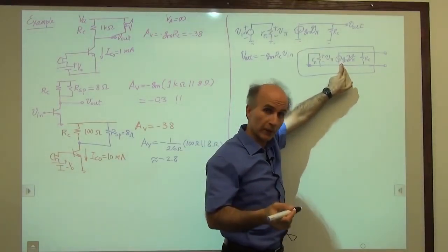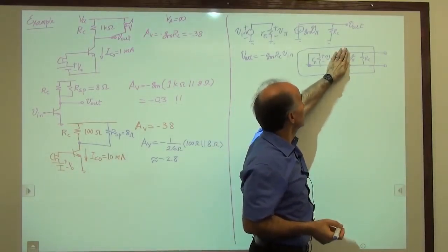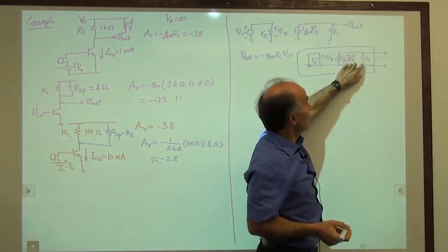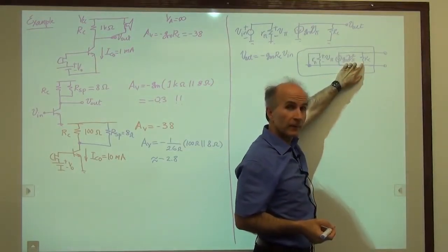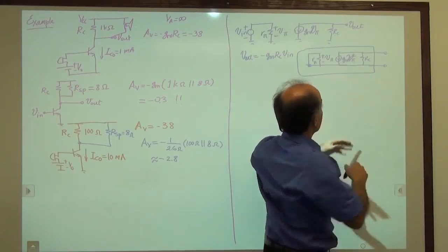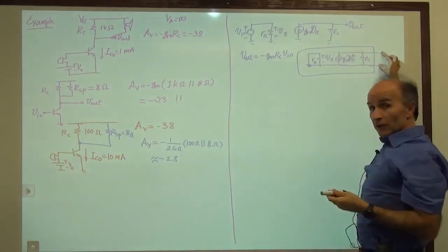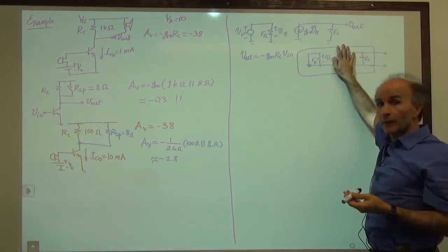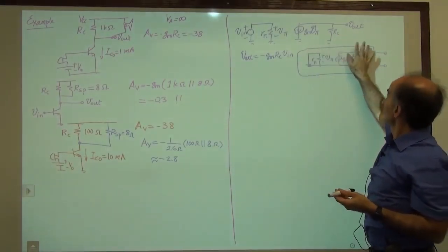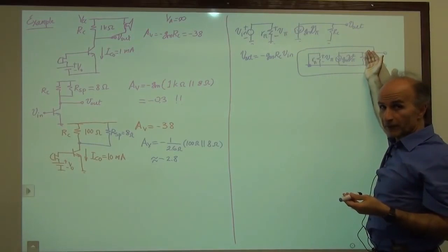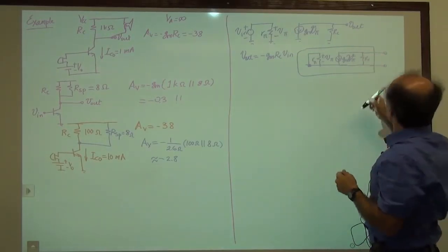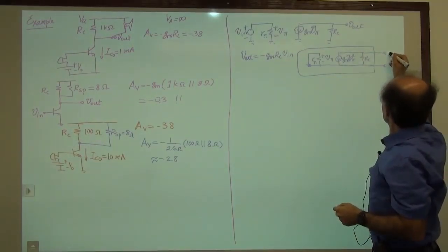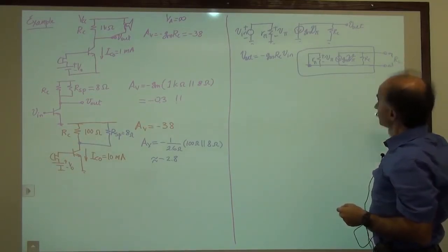It becomes an open circuit. So that's gone. And what's left? We have only RC left. So if I sit here and try to measure the resistance, I see RC. I don't see anything else. This is open. This is gone. This is not connected to this part anyway. So we have only RC. So the resistance that we see measured between these two terminals is RC.